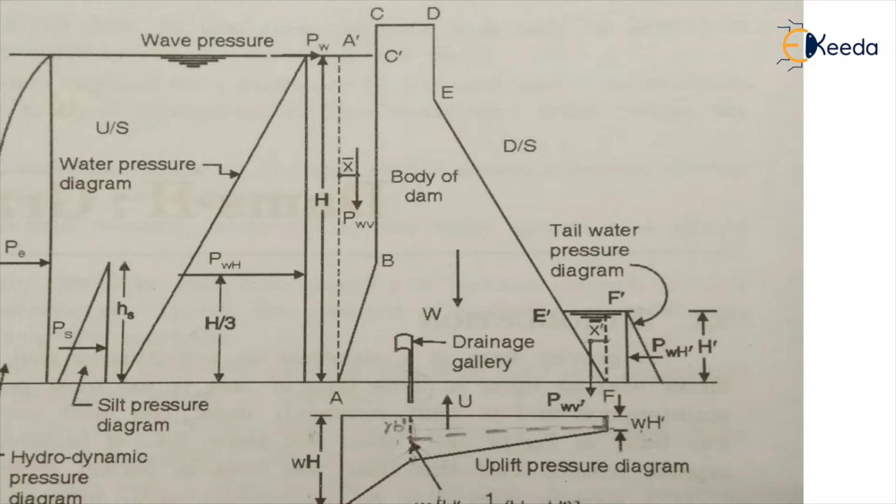So simply we draw a vertical upward line which coincides with the free surface level of the water. So we get one section, and again if I draw a horizontal line from the B section, I get two sections. The first one is a rectangular one on the uppermost side, and the second one is a triangular one. I know these are mathematical sections, and I know how to find the area of all these sections.